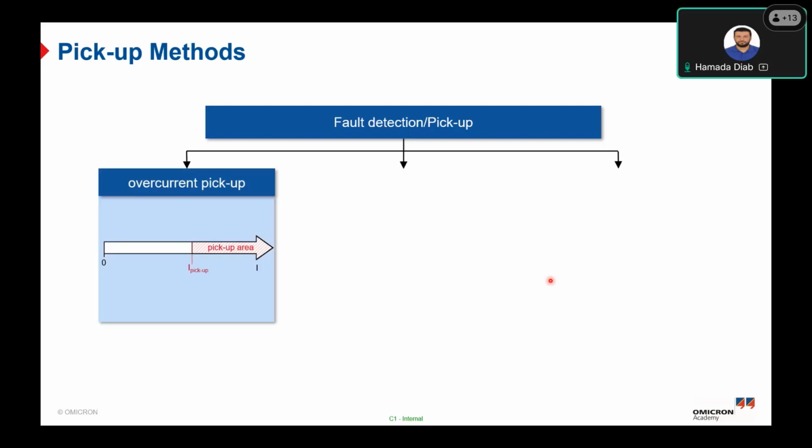As soon as the relay picks up, independent of the actual starter logic, it evaluates and calculates the impedance. And if this impedance is in one or more trip zones, the timer of the respective zones will be initiated. As soon as the timer has elapsed, the relay will issue a trip command to trip the circuit breaker according to the setting trip time delay.